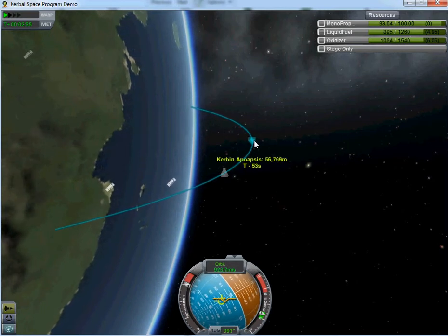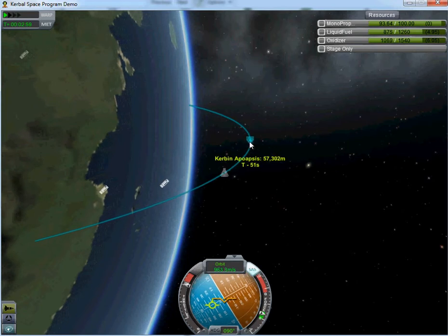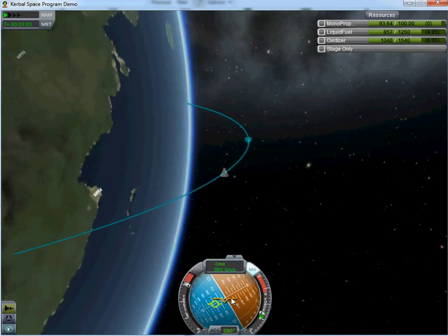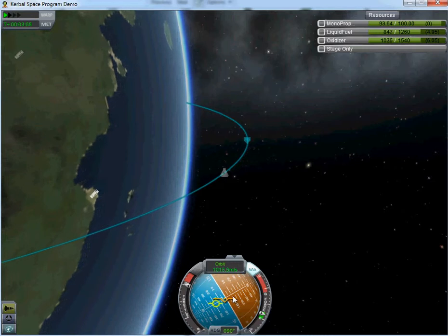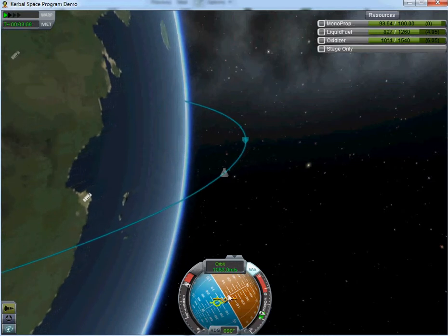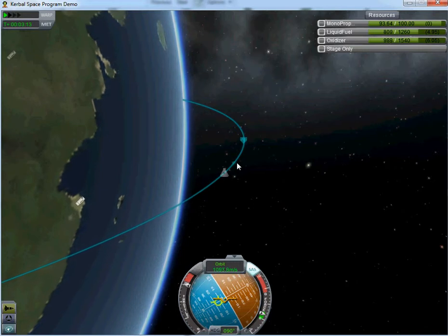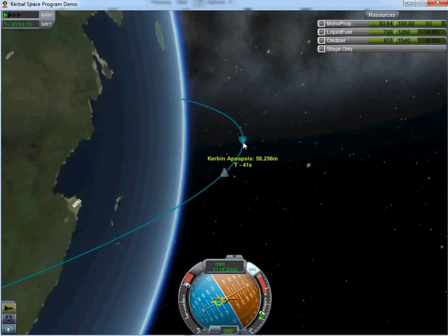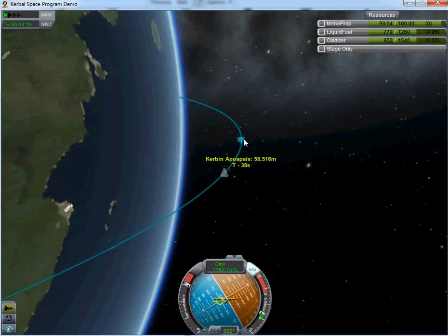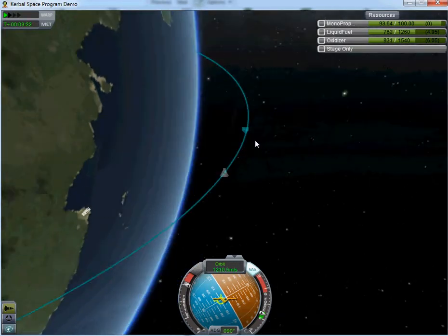So you see this part where it says 90 yet again here, where it has the difference between the brown and the blue: if my current indicator is showing that I'm in brown territory, then I'm actually nose down. I'm pointing towards the planet, which means I'm going to be decreasing my apex, or my apoapsis, of my trajectory. That would actually start decreasing, whereas we want to slightly increase it.